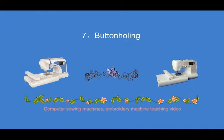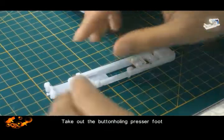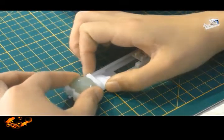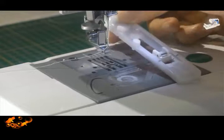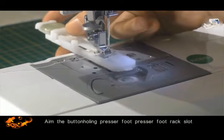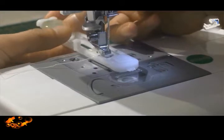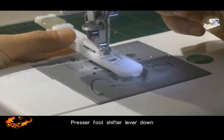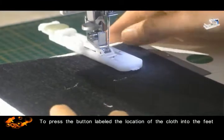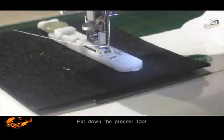Seven. Buttonholing. Change the presser foot. Take out the buttonholing presser foot, and set the button in the buttonhole foot to the selected length. Aim at the buttonholing presser foot rack slot. Press the presser foot shifter lever down. Put the cloth into the foot at the location marked for the button. Put down the presser foot.